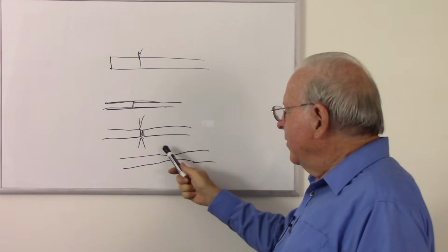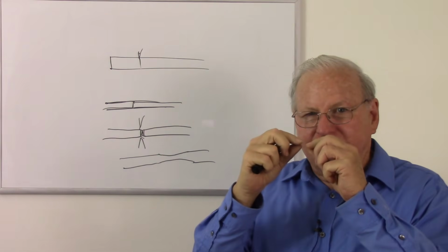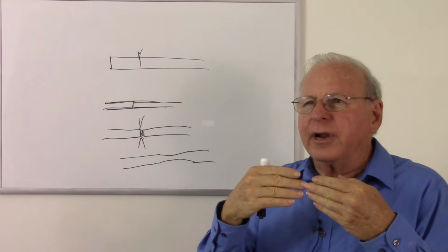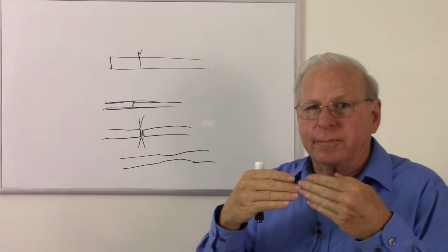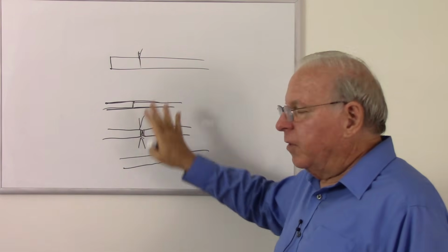Yeah, we don't want any debris of any kind on these fibers because we've got a very, very tiny light channel. That core is very tiny, and a little piece of dirt, debris, dust, smoke, or whatever is going to block that if we get it in there. So we have to be very clean when we work with these.